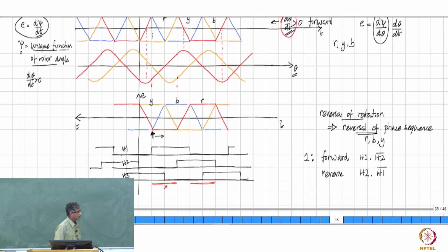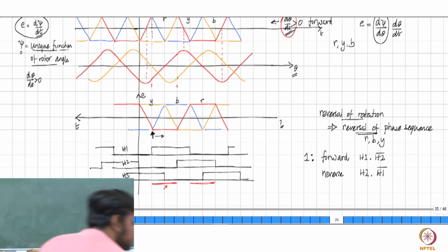Yeah. So this Hall switch, right? It only says whether the field is high or low, that's all. You cannot infer what the angle is based on the output. It is simply high, right? So this is not a mechanism that you can use to detect the angle of the rotor.